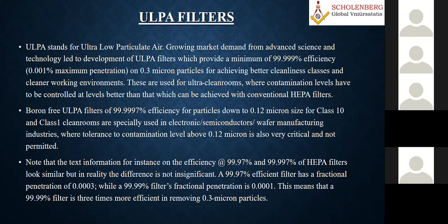It involves money. It depends upon your process. Some processes need this type of cleanliness level, but honestly, I have not designed that type of thing. This type of cleanroom may be required mostly in research applications or military applications, because they need very, very stringent control. Not even a small thing can they tolerate. So that type of thing only they use. But generally, for normal air conditioning, we have maximum up to HEPA filters.